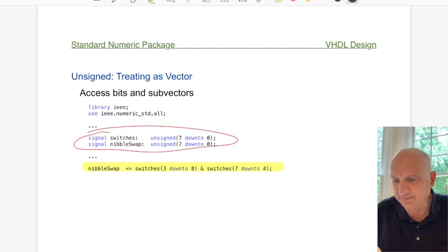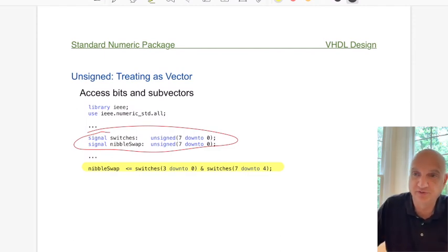Obviously, if you're creating, let's say, an ALU inside your VHDL module, you would definitely want to use signed and unsigned, because that makes the job of creating an ALU easier. It does both bit manipulations with shifts and the like, and also computational things like adding and subtracting. So it just fits. That's perfect. But most of the time, you're not going to be doing that kind of thing in your design, and it might stray you away from better practices like standard logic vector and integer. Most of the time, that's what you're going to use.